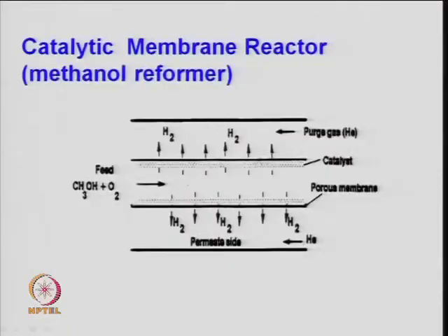So, it means something is to be done, in order to increase the conversion, increase the productivity and also increase the life of the catalyst. So, a new concept may be something like this. Instead of a packed bed reactor, presently this reforming is done in a large number of tubes, right, placed there, or in a single reactor. So, it is very difficult to dissipate the heat, or you need a good heat exchanger, that is a problem. Simultaneously, deactivation of the catalyst is a problem.